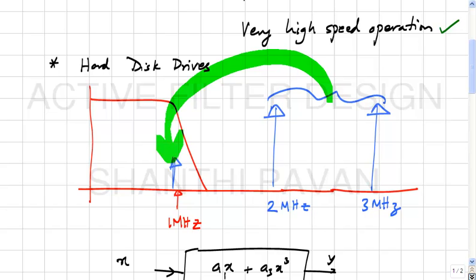Now if the filters inside were not very linear, finally this is all happening at RF, but everything has to be demodulated down to baseband, correct. I hope you all understand what modulation and demodulation is. Okay. So when you demodulate them down to baseband, your desired channel will be at baseband. Neighboring channels will not be at baseband, and so to get rid of those other channels, what you do is put a filter.